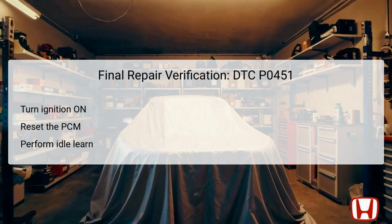Final repair verification is a critical step in ensuring that the repairs have successfully resolved the issues tied to DTC P0451. First, turn the ignition switch to the on position to prepare the system for diagnostic functions. Next, reset the powertrain control module, PCM, using the HDS. This reset process is essential as it clears any previous fault data stored in the module, enabling it to recalibrate and function correctly. Subsequently, perform the PCM idle learn procedure.